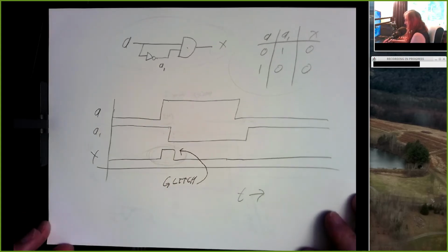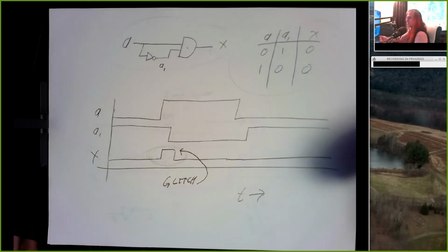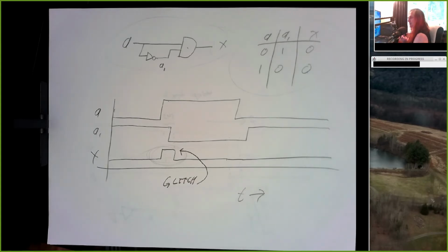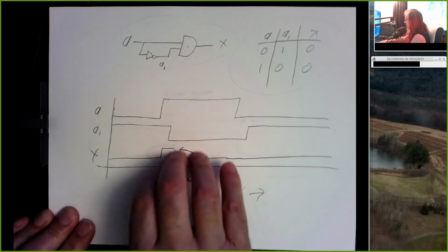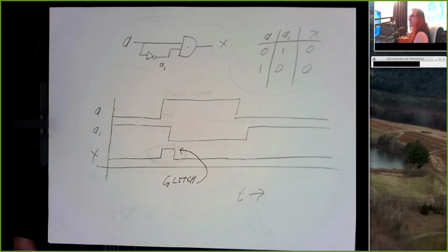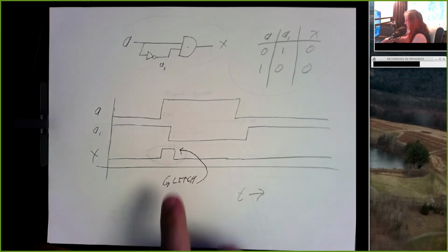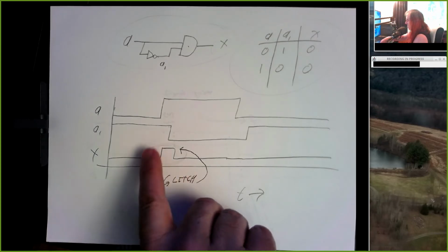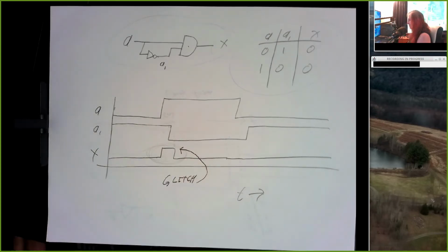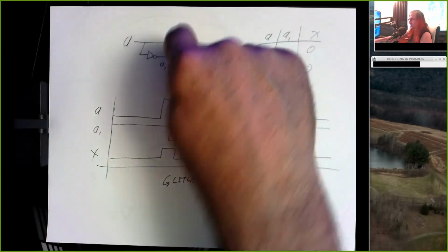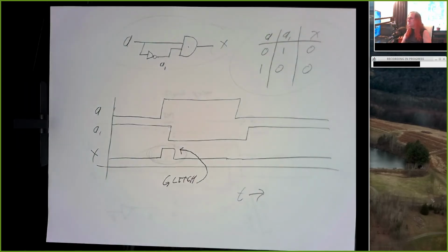So as we start to develop sequential circuits that have a memory, we'll start to worry about glitches, and the fact that these little timing anomalies can have lasting effects. If we have a circuit that remembers and changes its behavior if X is equal to 1, this circuit would cause some unexpected result.